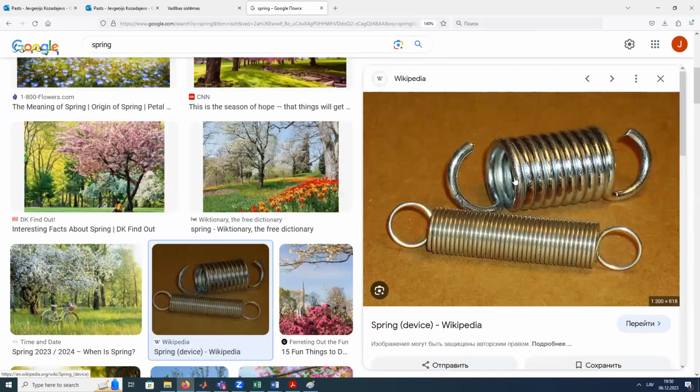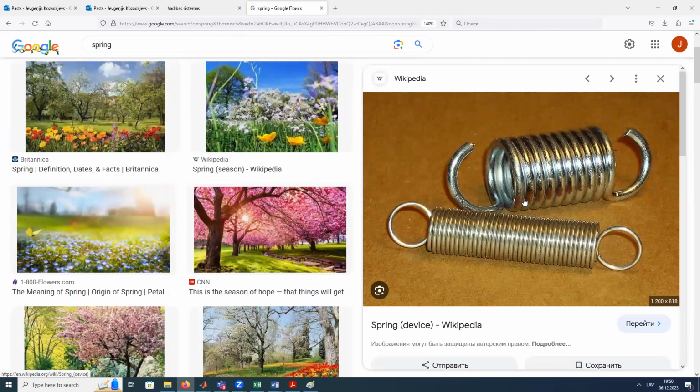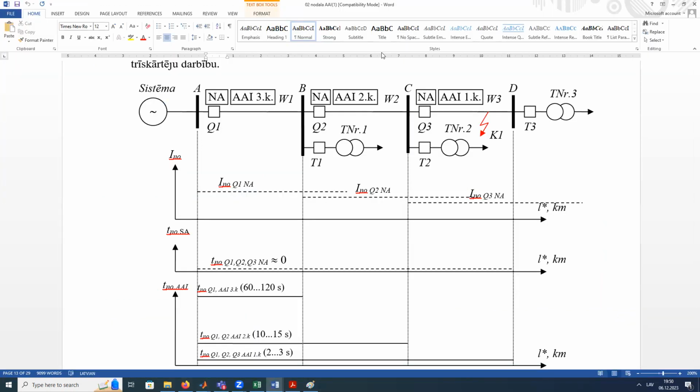So yes, we have kinetic power for a reclosing for a power switch in a spring. Yes, it's the right word. So what is the idea? The idea is when we don't have enough power for a power breaker to be ready after the reclosing. If you have a substation, in case of any fault, you have batteries on a substation to make the substation operate, or the relays to operate power breakers and so on.